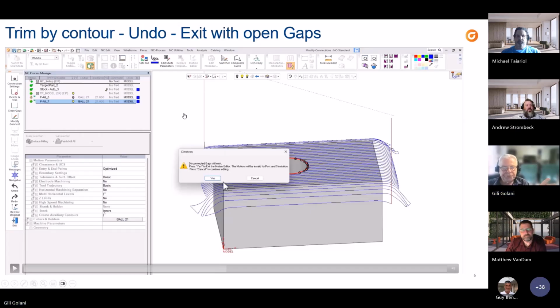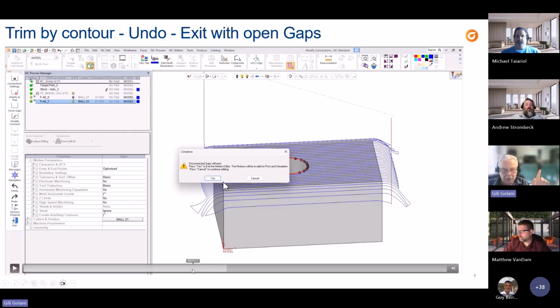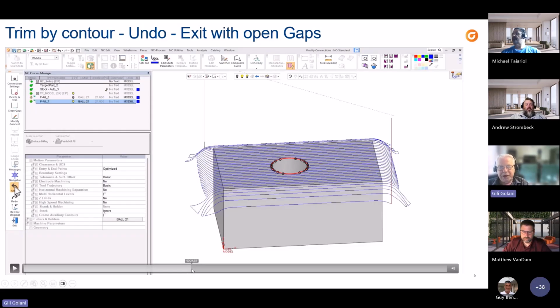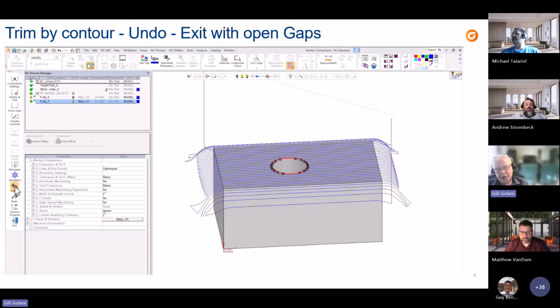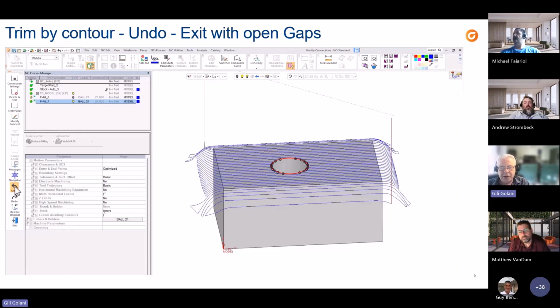And what I was trying to do, let's go here. Now I have open connections. As we know, an open connection is not a legal toolpath, because if this connection between that point and that point is open, it means that the cutter cannot disappear at one point and appear again at a different point.